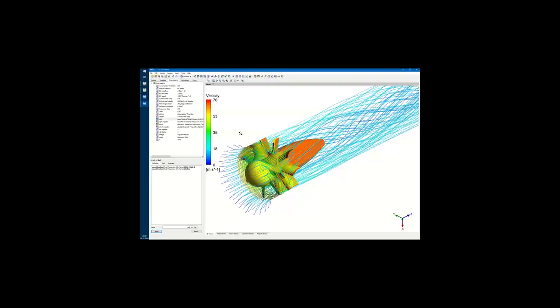Next question: for a pump design, can the design be imported back and forth between a CAD system as well and then moved to Ansys? Yes. The way it works today is the following. We import a CAD file, a STEP or Parasolid file for example, into CFturbo, or it could also be STL data, so we can read it in.